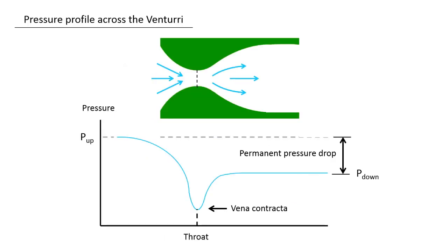Venturi is the same, a type of nozzle, but it's fancier, and it has shapes that follow the shape of the velocity here. But it happens to be the same. So the upstream pressure drops to its lowest point here, which they call the throat, and then recovers some of it. And that's the delta P we are dealing with in these flow control devices.